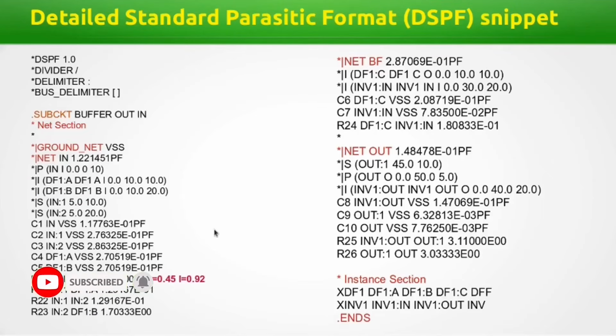Here, the snippet of a DSPF is shown. It will also contain a header section. The difference between the SPEF and DSPF is that the DSPF is ready for SPICE simulation. So there will be a sub-circuit definition. There will be a net section.